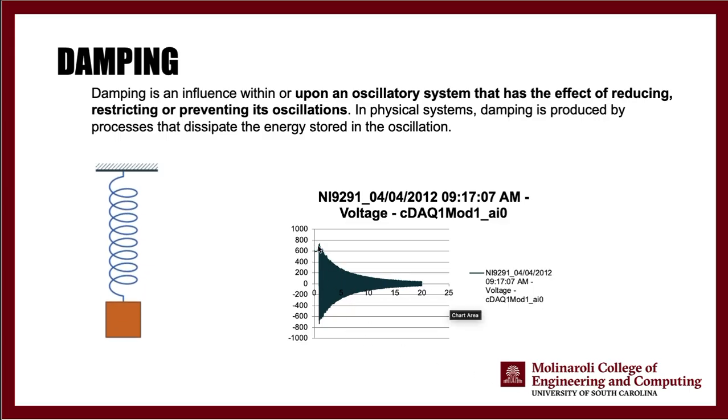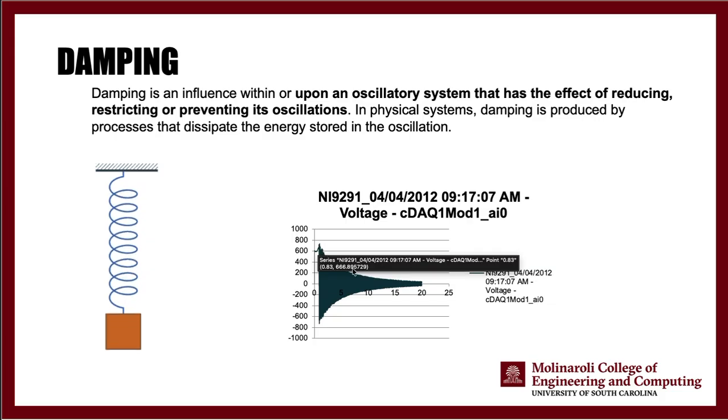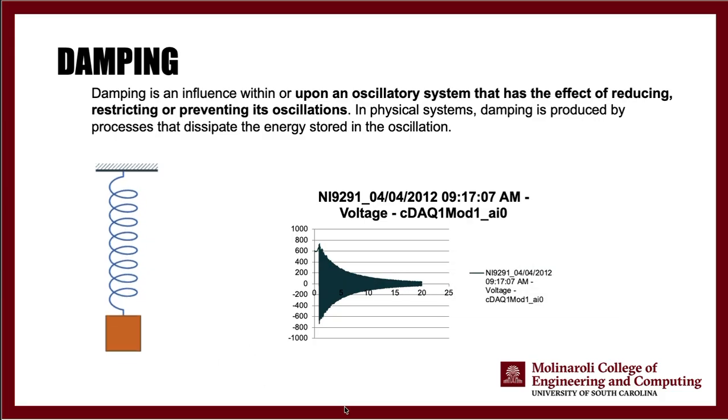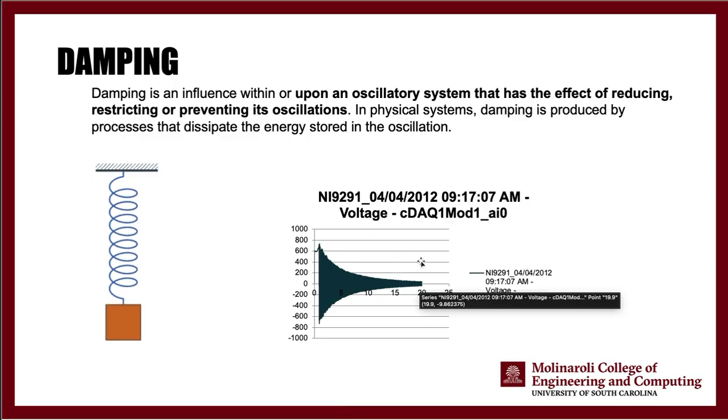You can see you start with a high degree of vibration, it will go down to closer to zero. You will be given a strain gauge that is already pre-installed on the beam, and that strain gauge connected to a DAQ and a National Instrument device is going to help you find this graph, right?